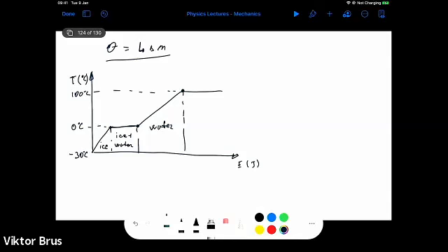That will go for latent heat until all water is vaporized. We get only water vapor, like steam. So in this region, we have water plus steam. And then we will increase the temperature of steam by providing more and more energy, until our container explodes or we stop providing energy.